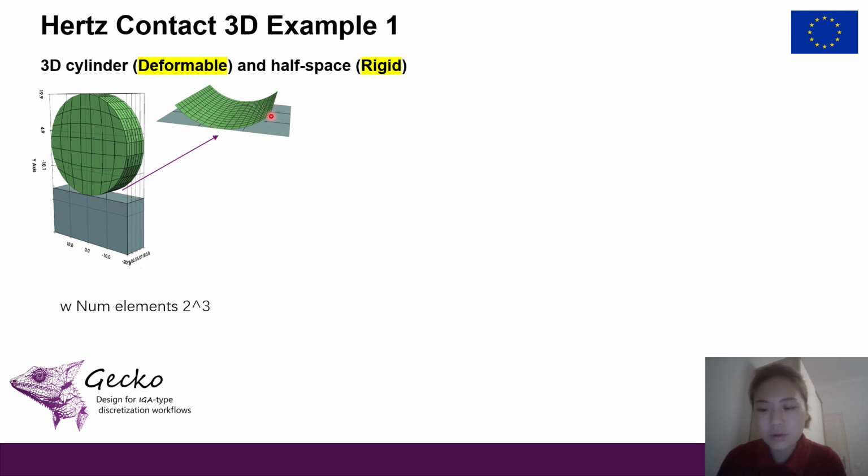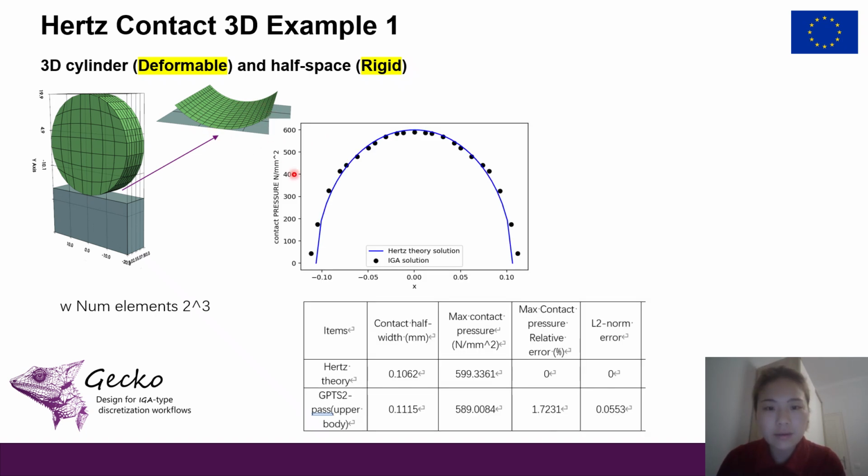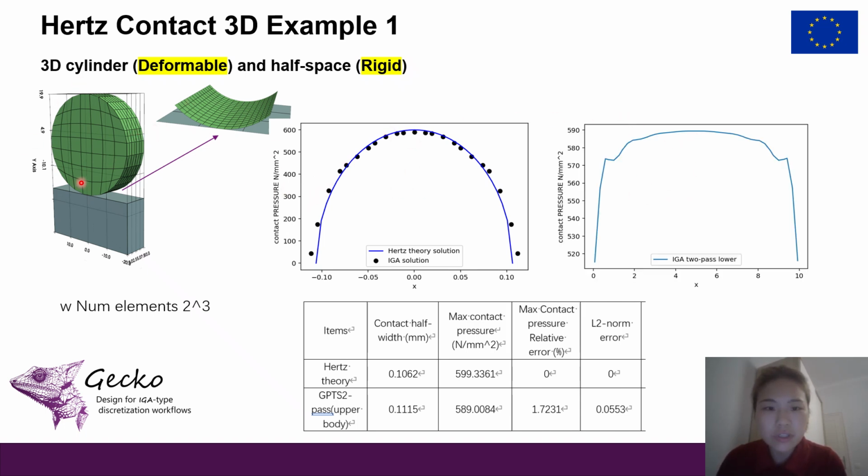We extract the contact surface, and here we see the contact pressure along the cylinder length shows a symmetric distribution. Because near the ends of the cylinder the surfaces are free, it allows some stress relaxation, so the value is smaller than in the middle. This highlights the importance of using the full 3D model to capture the realistic pressure variation along the cylinder length.